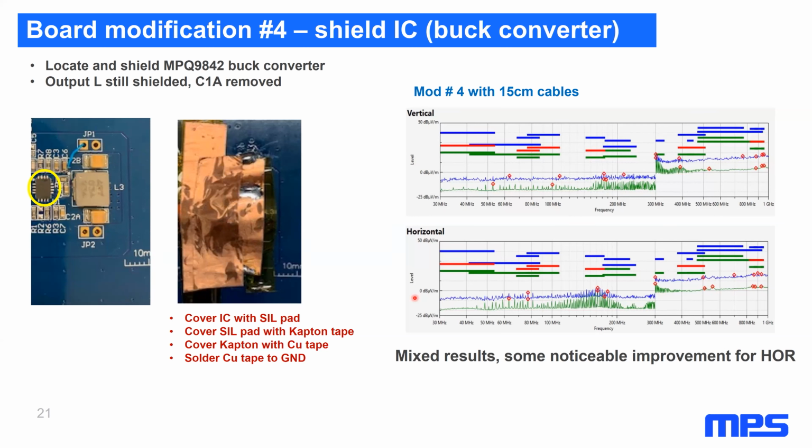And so I know when I'm doing this, I could be introducing other parasitics. There could be other parasitic capacitance I'm creating. I could be altering the magnetic or the electric field coming off the parts such that it's maybe propagating in a different direction. There's certainly all these things that could be happening.